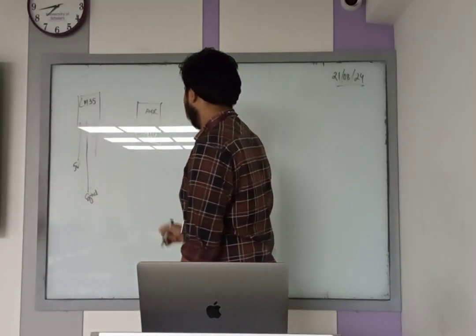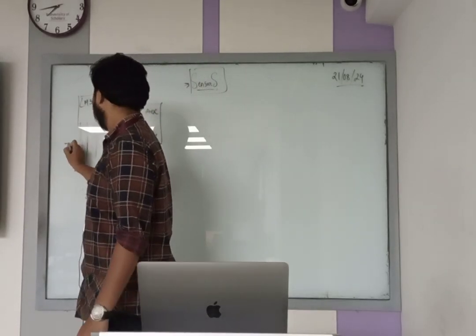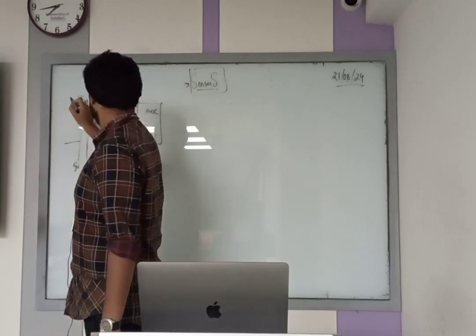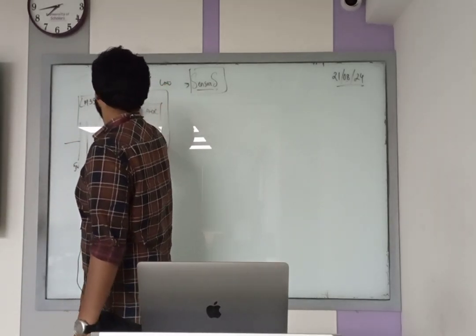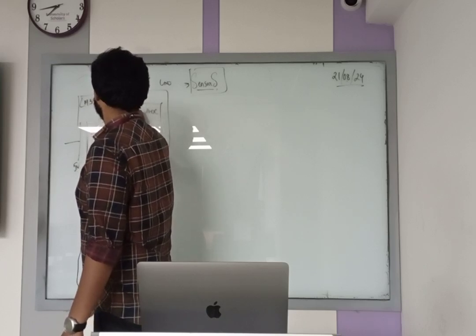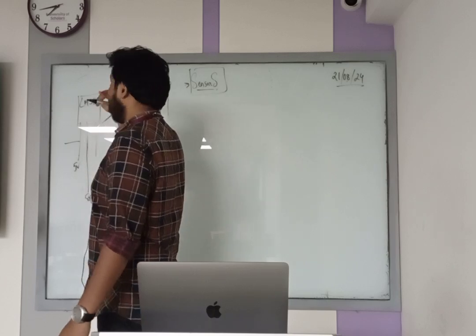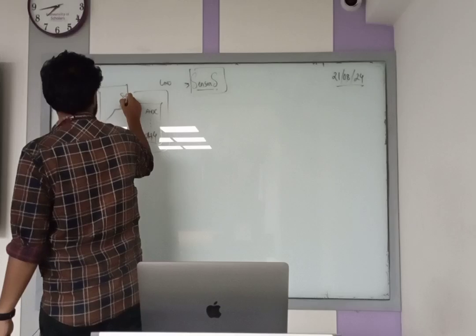So now you have to power up this 5 volt and ground. You may connect another battery source, or you may connect with the Arduino Uno. There's a 5 volt pin, there's a ground pin. You know that you have to connect the common ground as they're connected with each other. So you can connect this 5 volt over there.